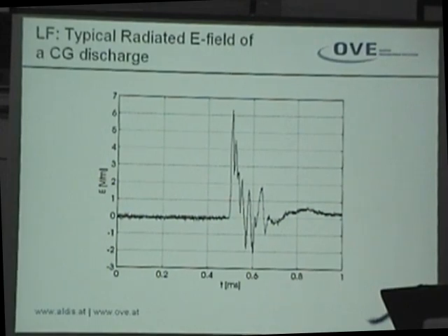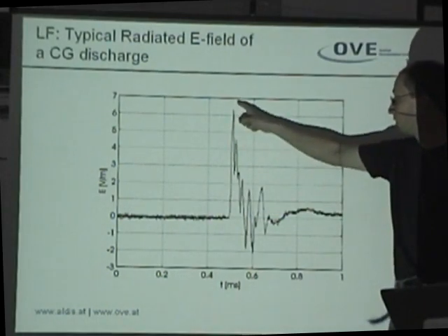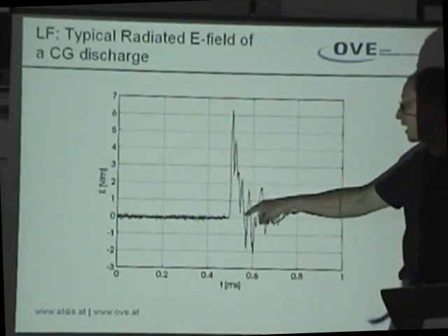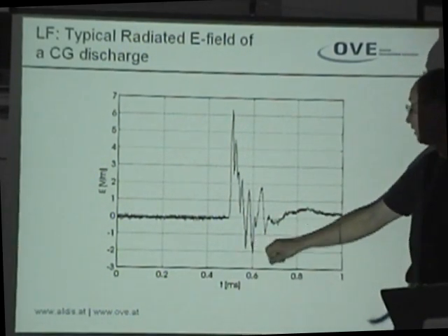How does the lightning detection system that we are using distinguish between cloud to ground and cloud to cloud data? It's basically based on the field waveform. Cloud to ground lightning fields have a very typical field waveform. You have a sharp rise in front, and for the first stroke some variation in the tail.